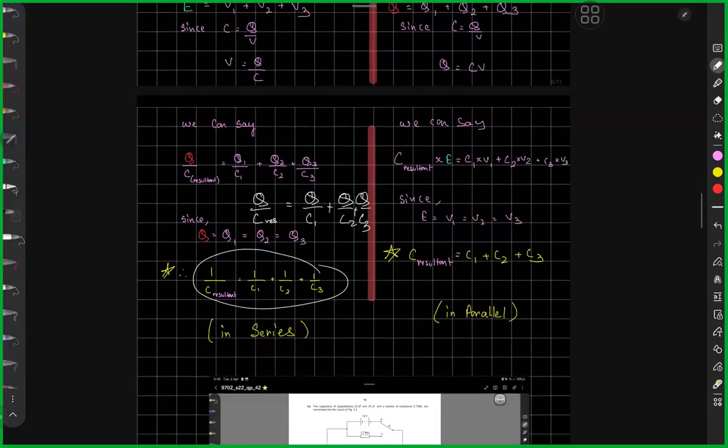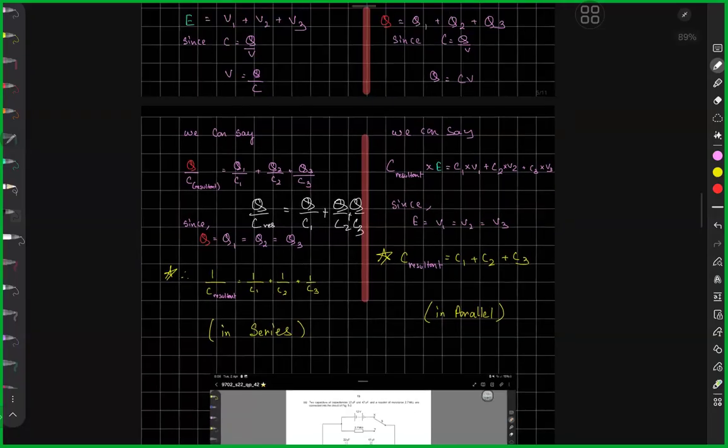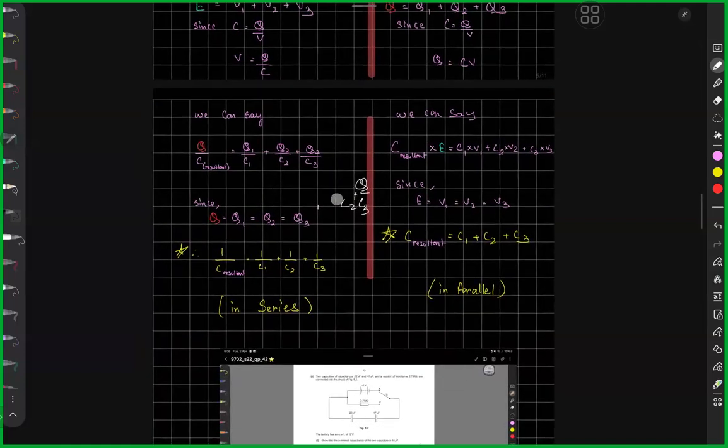So that is how you have this equation working. Very similar to the parallel resistor equation, right? The resulting capacitance will be less than all of the individual capacitances. That is something we have realized when working with the formula again and again. Okay. So that is the point. We add all the inverses up. Good. Okay. So that's the derivation. This derivation is needed. They'll ask you to derive this.